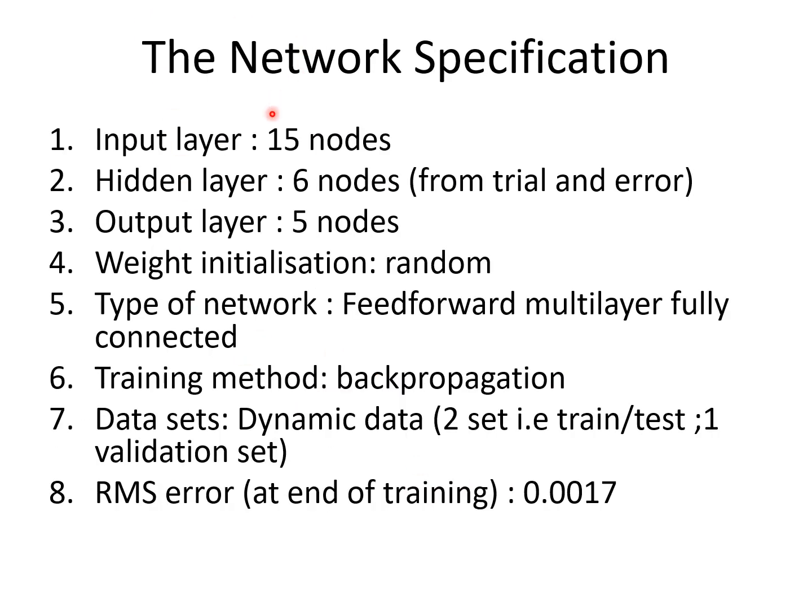So in this case, we have decided on 15 input nodes, because we're talking about future prediction. So we have C0 with its past data, C2 with its past data, and C0 future data. The hidden layer size is obtained from trial and error, and the output layer is the prediction of C2, the output concentration at this step plus the future ones, so it becomes 5 output nodes.